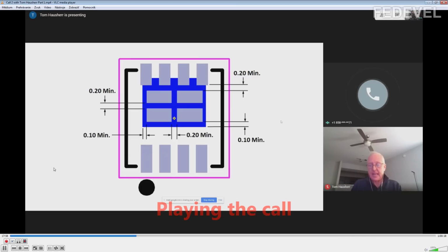The paste mask is like IPC 7. The IPC standards say the minimum paste mask should be 40%, and the maximum should be 60%. But we use 50%, but we allow the user to change it. But we have rules. When you say this percent, we are speaking about the exposed pad, the thermal pads. It is not for the standard pad. Standard pad is 100%. Standard parts, the leads are 100%. The thermal pads are reduced, by 50% or 60%.